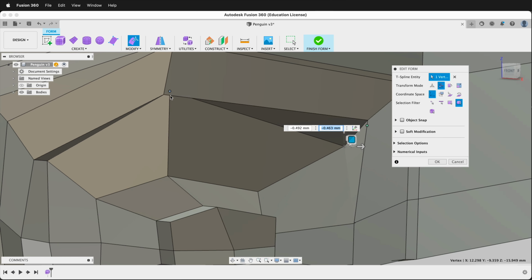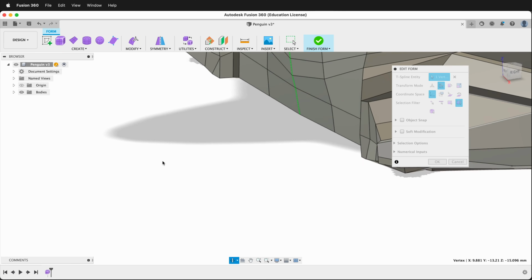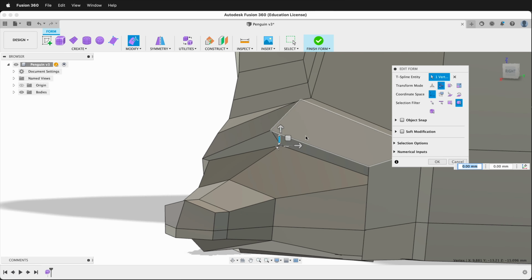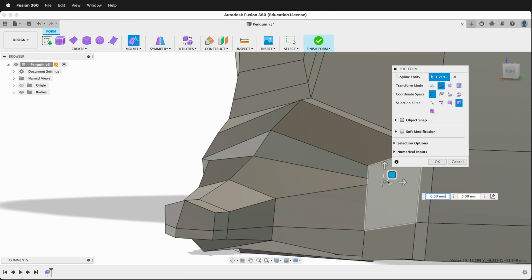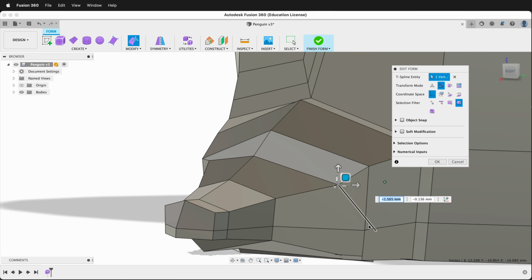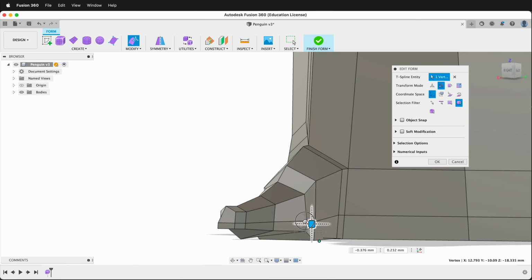So whenever you get these pieces that are overlapping, you can click and hold, and then grab that vertex from up there. And then that will work a little bit better. Then go to the side, and then you can pull it out the other direction. And then this one's back there too. So I've got to click and hold. I can grab that vertex, and then I can pull that out and see how that helps everything. Looks like I got one back here too. So I'll bring that out. And then once we get all this, those feet are going to look a lot better.